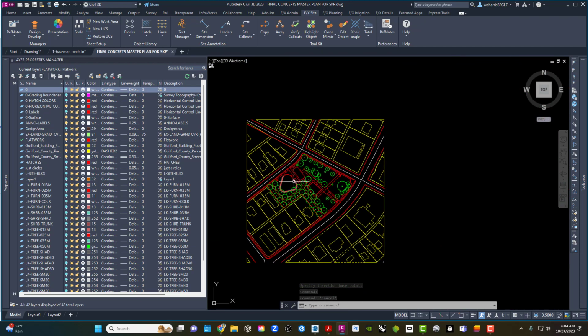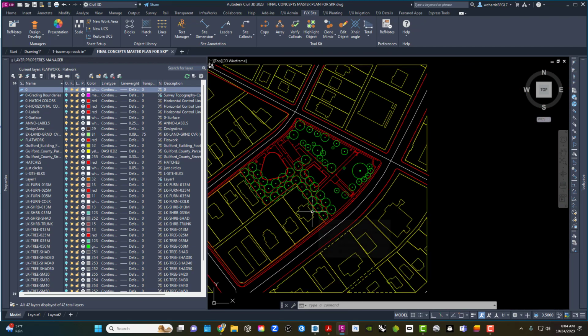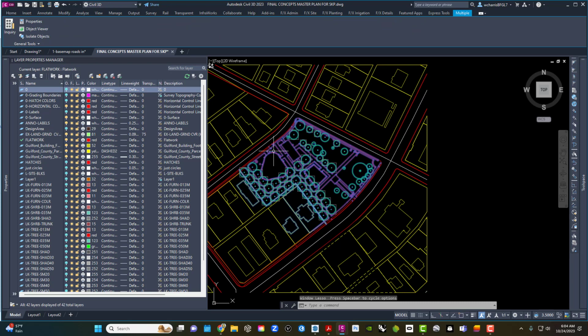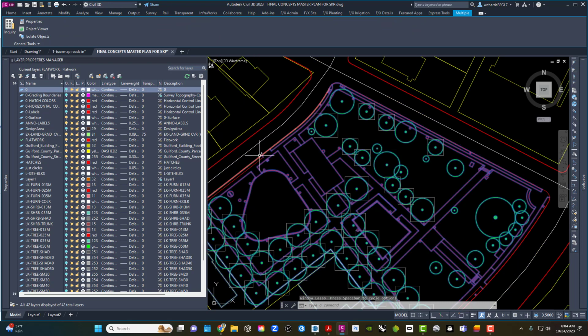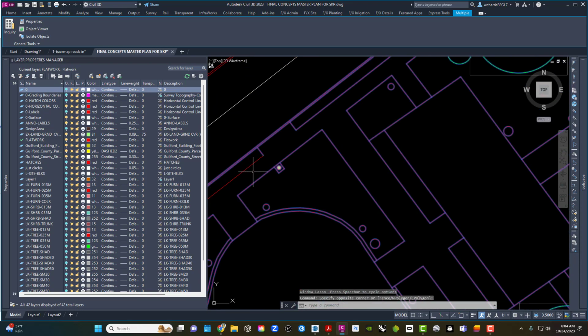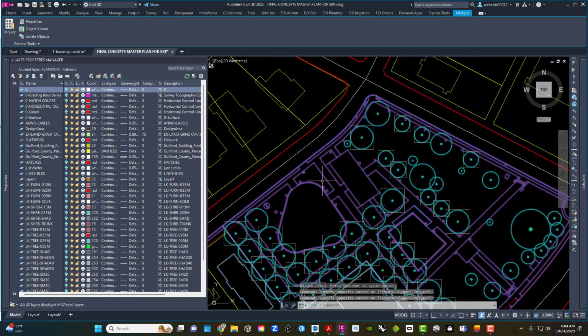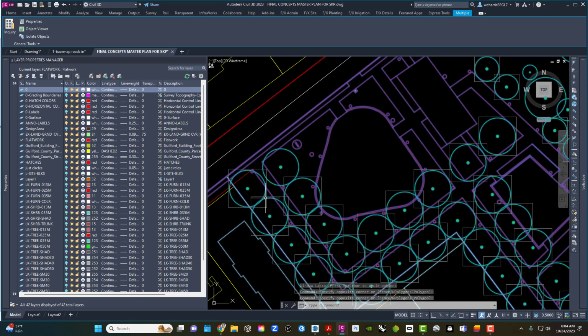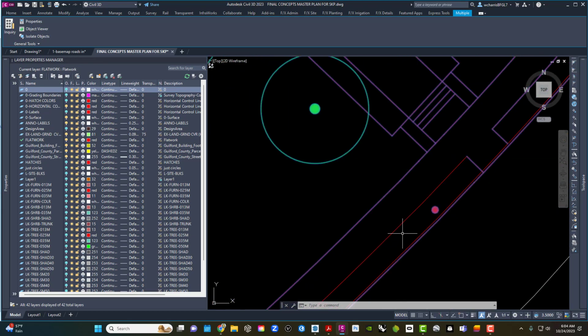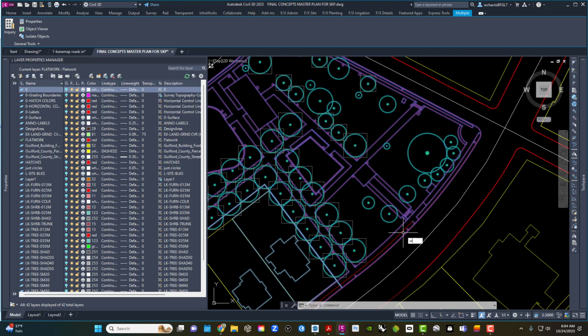So once I have this, I don't need everything, but I'm going to click and hold and just drag my line around. I think she did it in a way where I could just pull over her line work separate from the flat work, but just in case your flat work or your horizontal controls from your survey, you modify for some reason, I'm just bringing over a chunk of the site, and I'm going to do that by doing a W block.